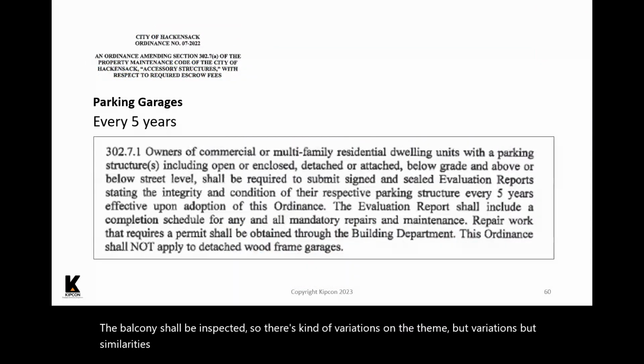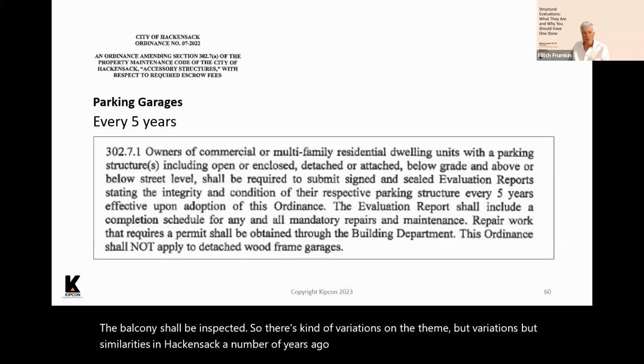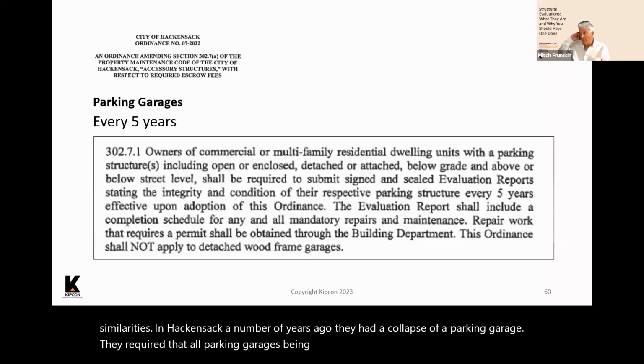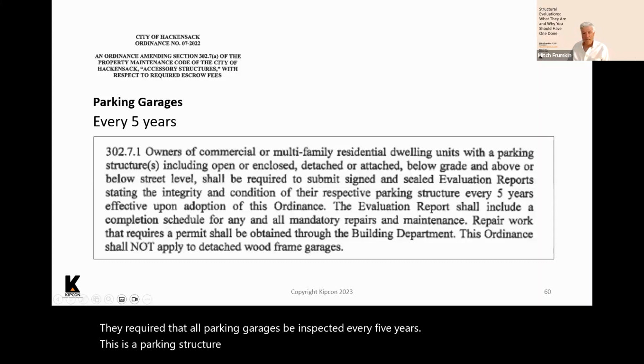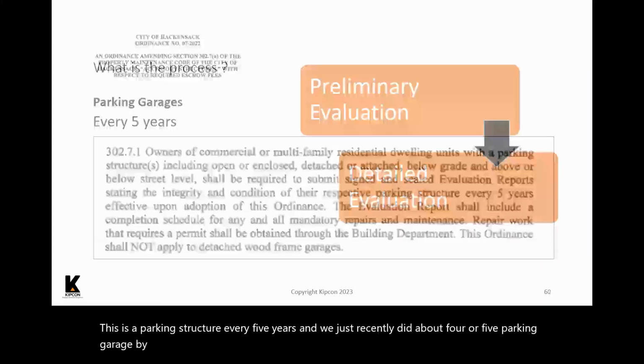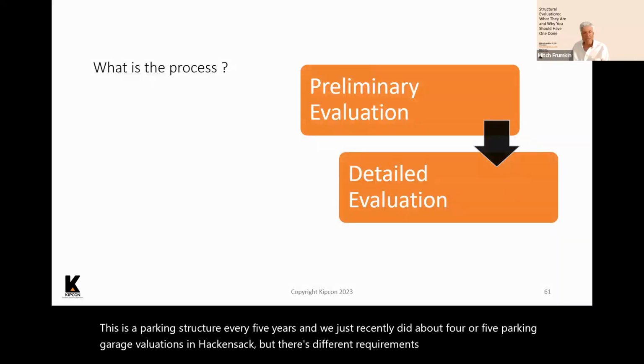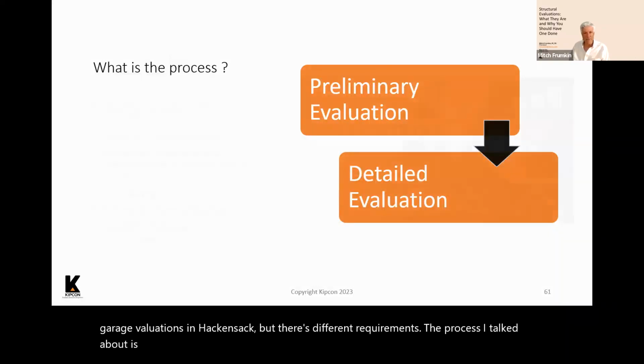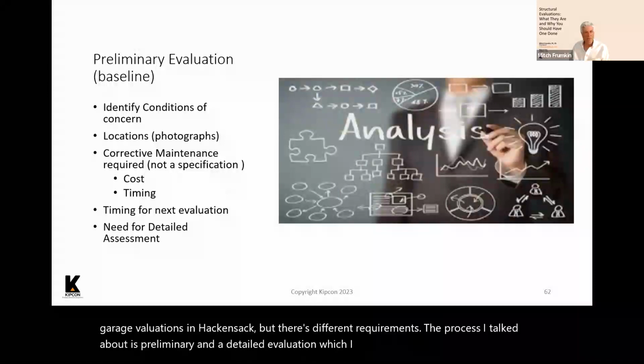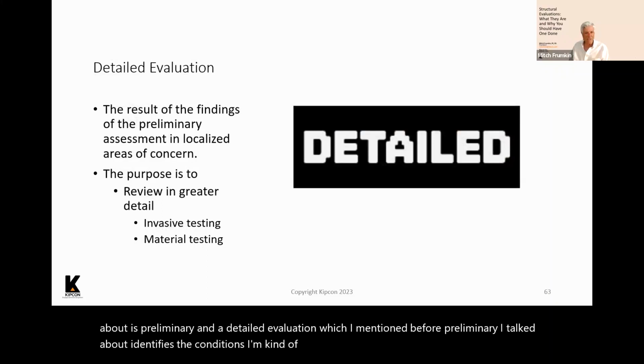In Hackensack, a number of years ago, they had a collapse of a parking garage. They require that all parking garages be inspected every 5 years. It says parking structure every 5 years. And we just recently did about 4 or 5 parking garage evaluations in Hackensack, but there are different requirements. The process I talked about is preliminary and a detailed evaluation, which I mentioned before. Preliminary identifies the conditions. I'm repeating some stuff. Now, detailed goes into more detail.